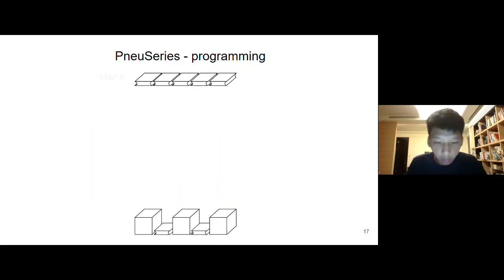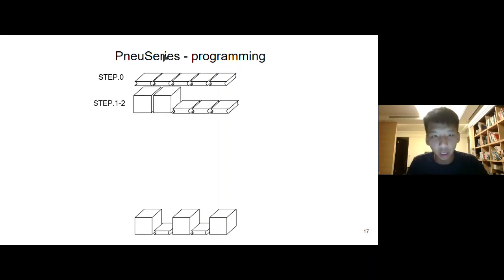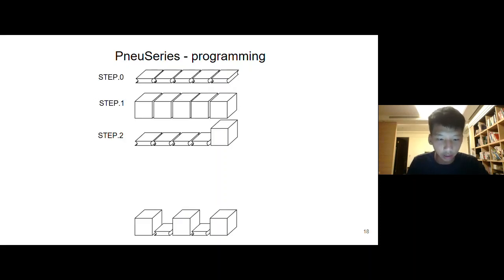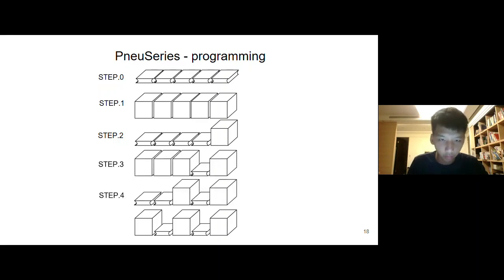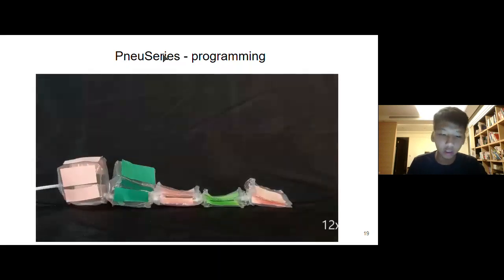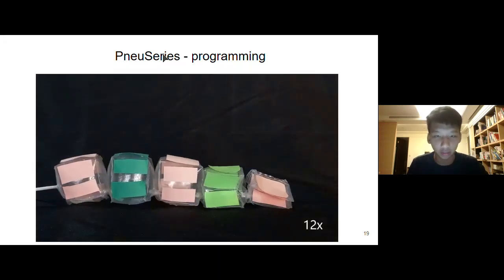To reach the target shape, we divide and conquer to make the rightmost inflatable match the target shape. That is, the system keeps pumping in until the rightmost is inflated. As the rightmost is inflated, the system then considers the second rightmost and so on. So we inflate the inflatables one by one until all inflatables reach the target state. Finally, that's what we saw in the video from the beginning.